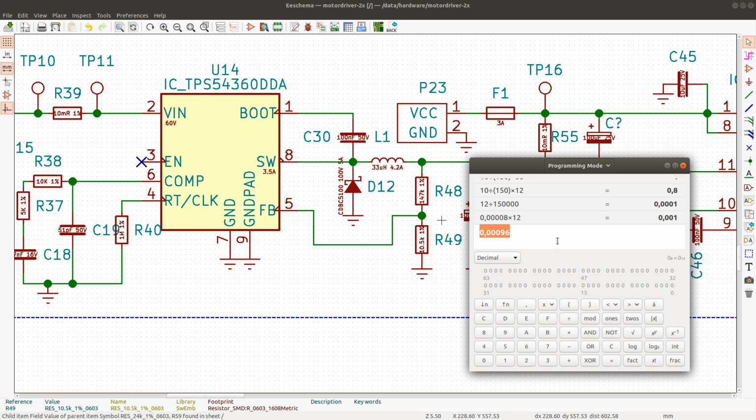So if I then have 0.8 volts on the bottom resistor divided by 10,000, which should give us the current, and then times 0.8, so I get, right, so this would be 64 microwatts of power dissipation in this resistor.